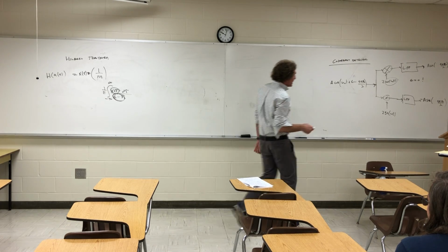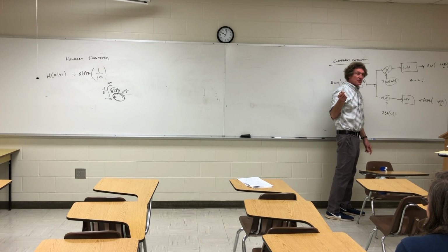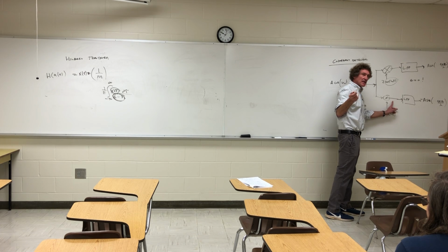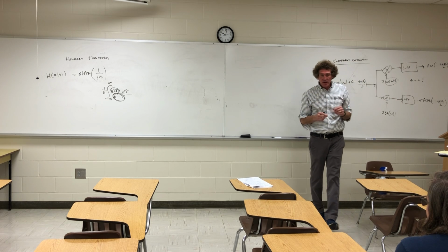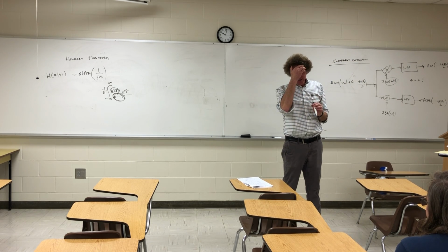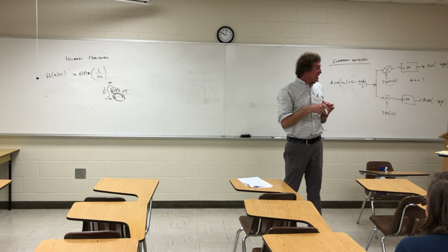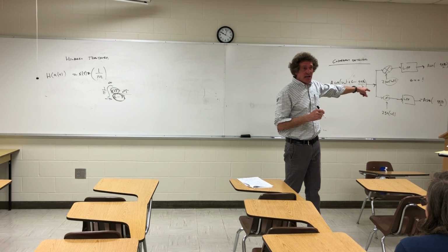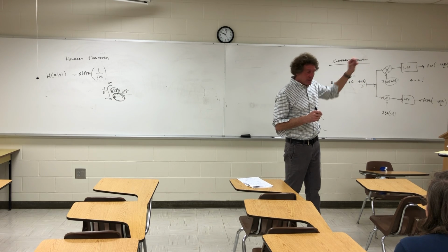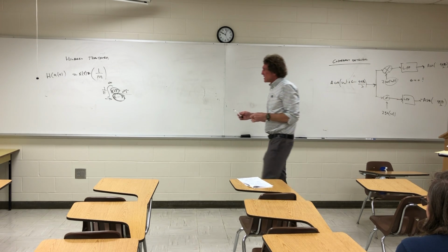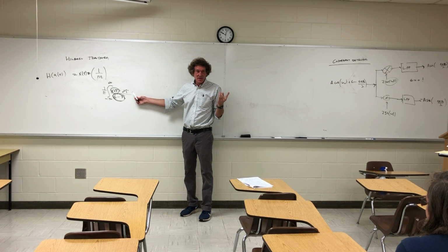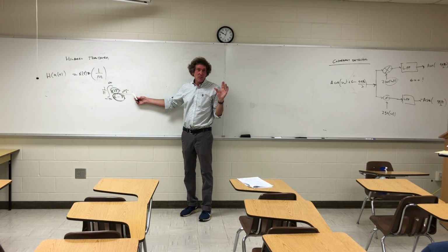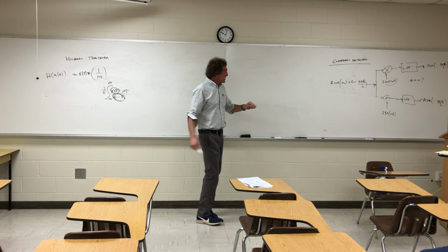And frankly, I want to level with you, the Hilbert transform operation can be done up here, but it requires an enormous amount of data, so it's usually done right here. I think it subtracts 90 degrees. Yeah, I'm sorry. It subtracts 90, but that side is actually the negative of the Hilbert transform of the signal, the in-phase signal. But here's the real thing too. You'll notice to do this, I don't need a second stable local oscillator. I mean, I don't need to do something where I get a time shift right here.